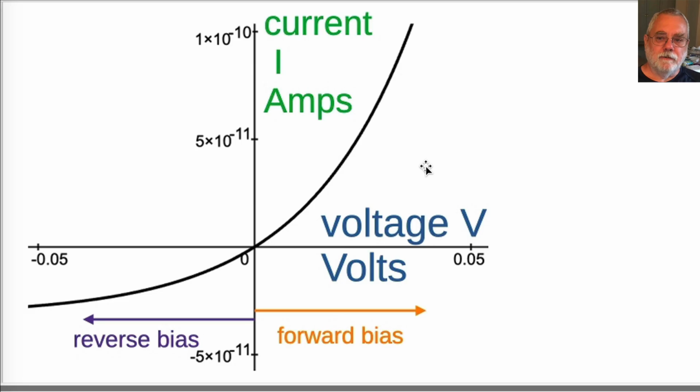Power is positive in the upper right and lower left quadrants. The diode is dissipating power at all non-zero voltages. The power is provided by a connected external circuit that results in the voltage. The dissipated power heats the diode.